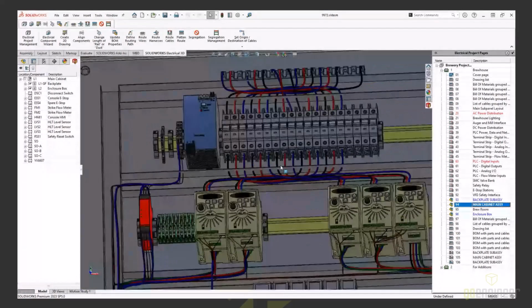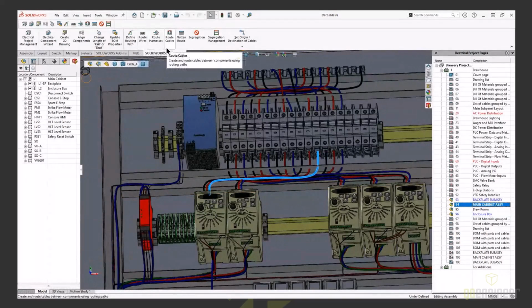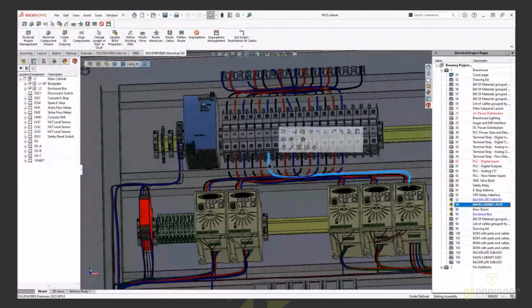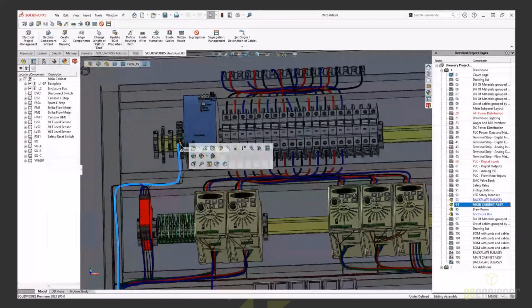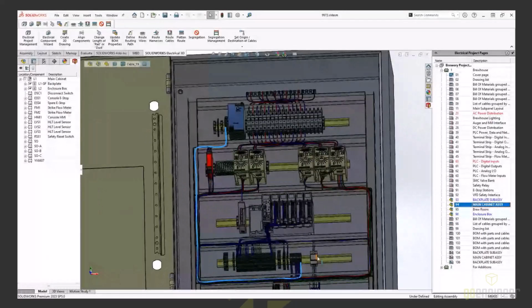So as I zoom into this model, this one has already had the wires run, and mind you, the information is stored in the model. It's stored in the schematic. So when I route the wires, I'm not having to draw each one of these individually. It's a command up here of either routing wires, harnesses, or cables. So we essentially get everything defined, and then we tell it to run the wires. There's obviously some training behind the scenes that goes on there, but it is a true point to point. So we're coming from one device all the way down to the other device, and it is capturing that information of where the wire is going.